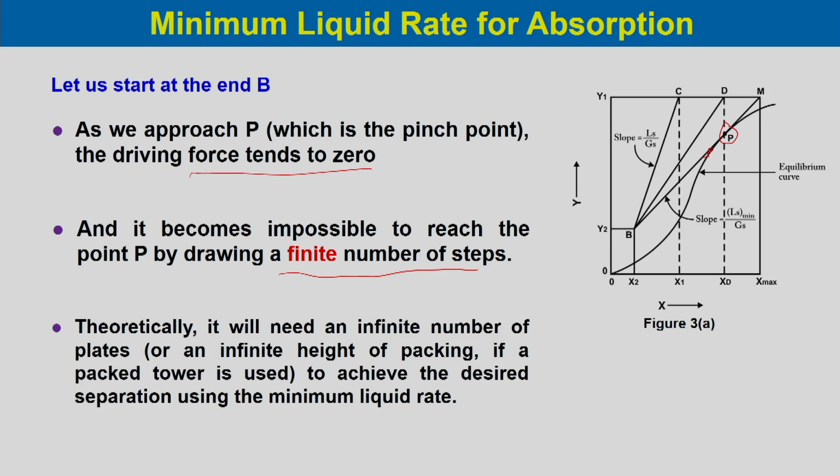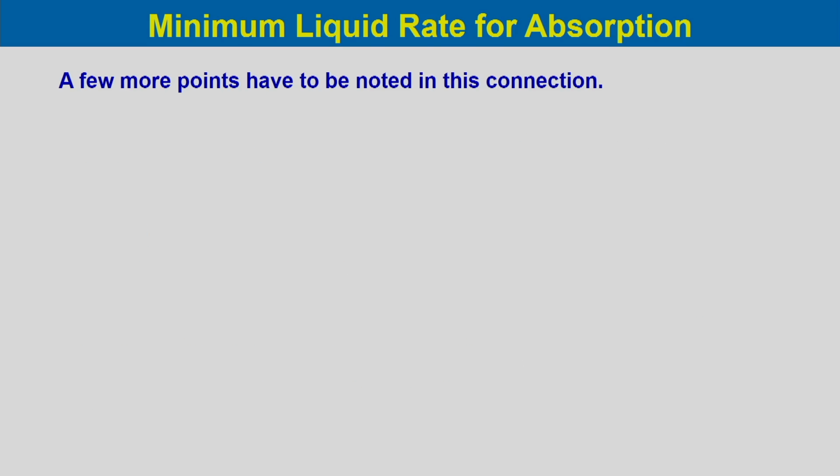So, theoretically it will need an infinite number of plates, or an infinite height of packing if a packed tower is used, to achieve the desired separation using the minimum liquid rate. So, for practical applications we have to run the absorber at more than the minimum liquid flow rate. A few more points have to be noted in this connection.